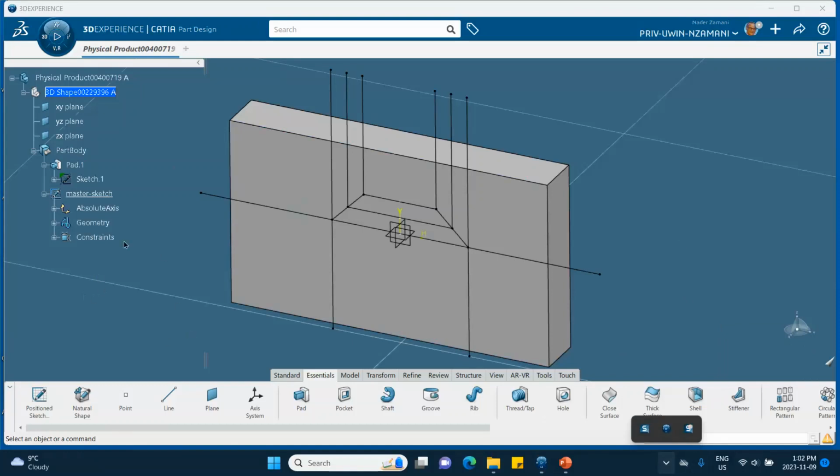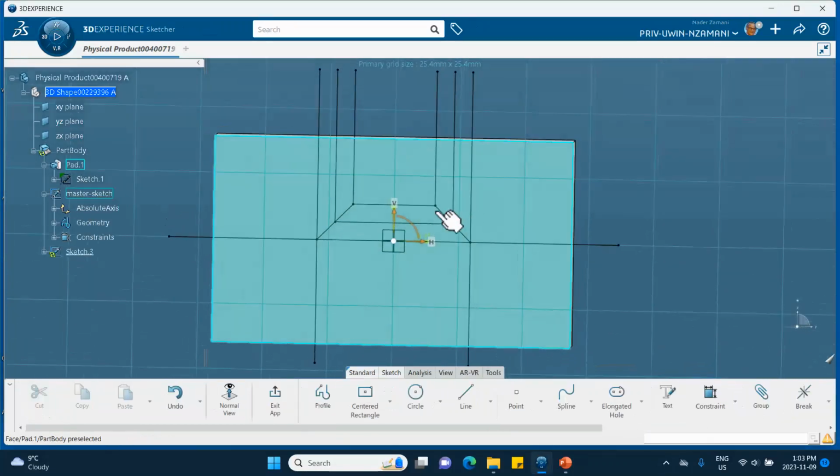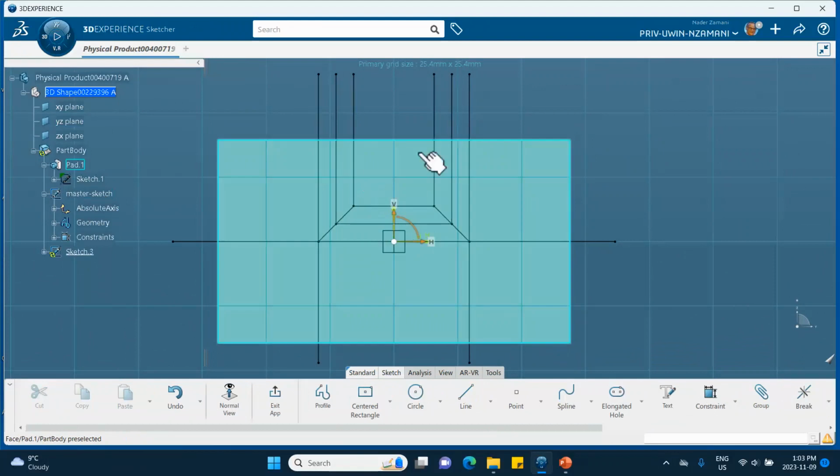Okay, then I'm going to create another sketch, and in that sketch, I'm going to project these combs, vertical upward combs. Okay, so I'm going to create on that same plane. I will sketch, and I'll change the name of that, of course, to comb, vertical comb. How about that? So let's project these edges, these curves onto that sketch.